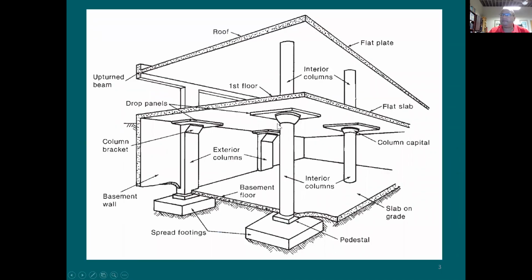When you look at this system here, you say, let me put some point load here in the middle. Let's say I'm going to put a heavy piece of equipment on the rooftop, like an AC unit or whatever. How does the load move to the columns? Is it going to go to this column, the other column in the back, and this column also? Is it moving in all directions, in two directions? Some load going this direction, some load going that direction? Or does it just go to some beams? I don't see any beams here. So the load is going to be moving in both directions, if you like to call them X and Y. Here's the X direction, the Y direction. Yes, the load is going to be moving in two directions.